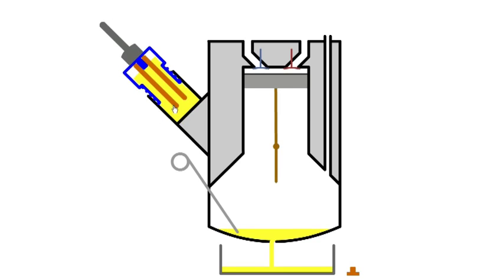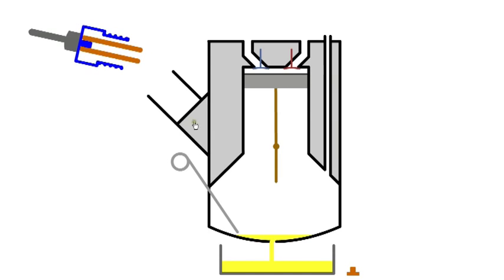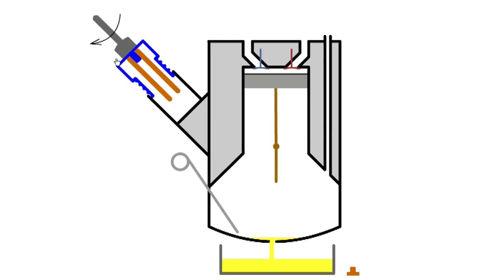It's sometimes called an eco-filter, as only the element is changed, saving on material and disposal costs. When the filter housing is unscrewed, a hole opens in the housing and allows the oil in the filter to drain internally to the sump. The element contains no metal parts, it's manufactured from paper and plastics, and is suitable for incineration, capturing heat from the waste oil. The new filter and O-rings are fitted and the housing is tightened to the correct torque.